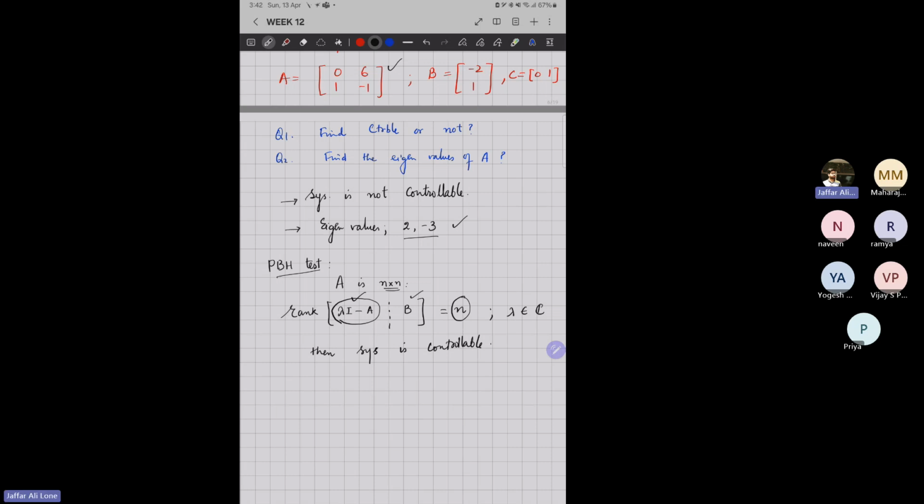So see this, when can this lambda I minus A be 0? It will only be equal to 0 when my lambdas are eigenvalues of matrix A. Why? Because in that case, this will become the characteristic equation, right? So when we find the roots of this lambda I minus A, they are the eigenvalues of my system.